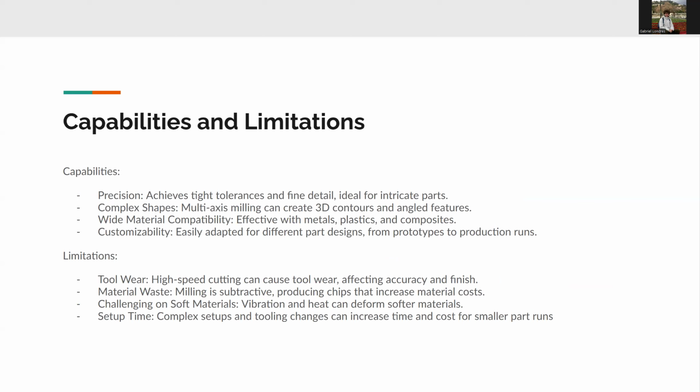So, a couple capabilities and limitations. It's very precise, it can create very complex shapes. There is a wide material compatibility and it's very customizable, as I said before. A couple limitations are that the tool wear is quite high. The material waste can be high depending on what kind of milling you're doing, and it can be challenging on soft materials. And then the setup time can increase time and cost for smaller part runs.